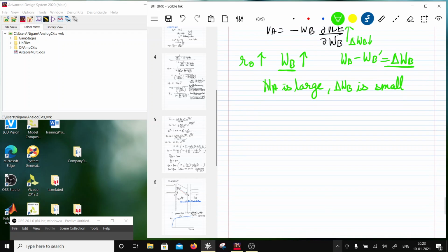Now we have seen what a small signal is. Now let's see a small signal model. So let me construct a model here. In the model I am going to have some extrinsic resistance, and I can also have some lead inductance. So this is, let's say, RB. Then I am going to have C pi and R pi.